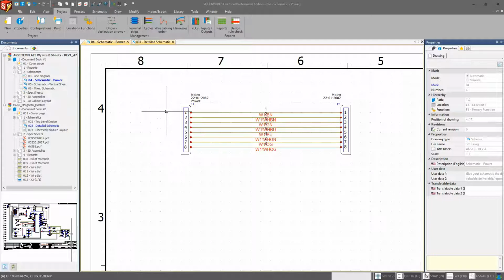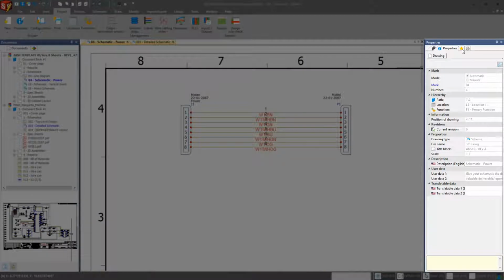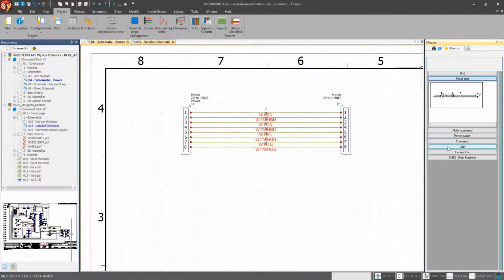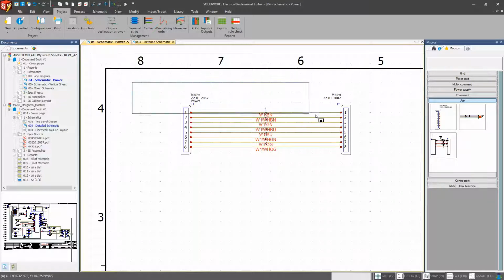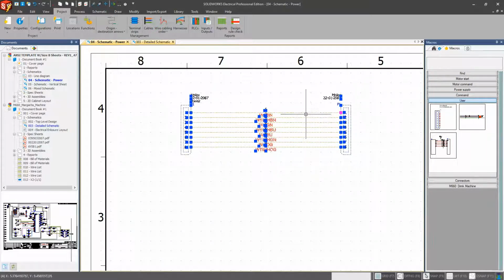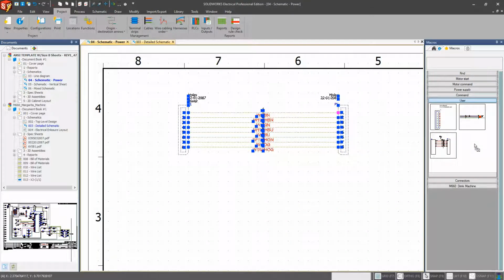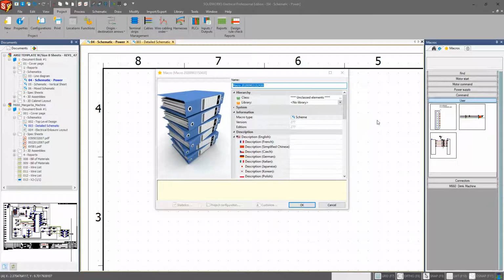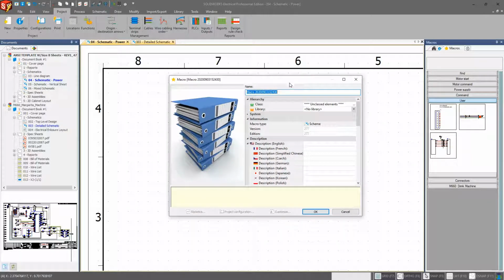So getting started, we have our basic little circuit here. It's our harness now because we've turned it into a harness. And in order to turn this into a macro, we need to simply select the star icon, the tab, and we can take this entire circuit. We're going to highlight everything associated to it, and you have to click on one of the parts. You have to click on the wire or the edge of a connector and simply drag it over, and wait till you get the plus sign with your cursor. And now you're about to add it to your library.